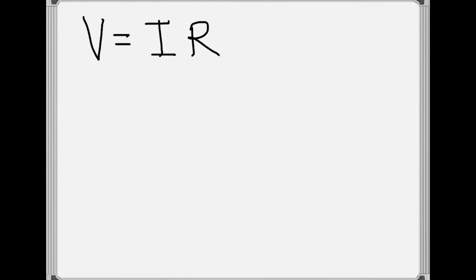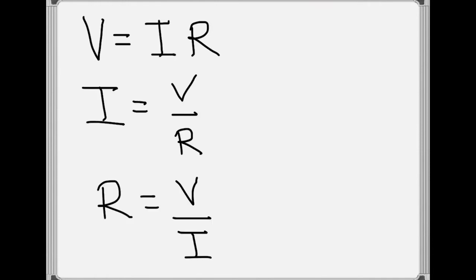Now, this is not essential, but I've gotten into a way of working which is that I want to be thinking more about the problem than continue to rearrange Ohm's law. So I always think it's a good idea that I write out Ohm's law with each of the parts as the subject of that equation. So we've got V equals IR, I equals V over R, and R equals V over I. But that's just my way of working. It's entirely up to you whether you do that.